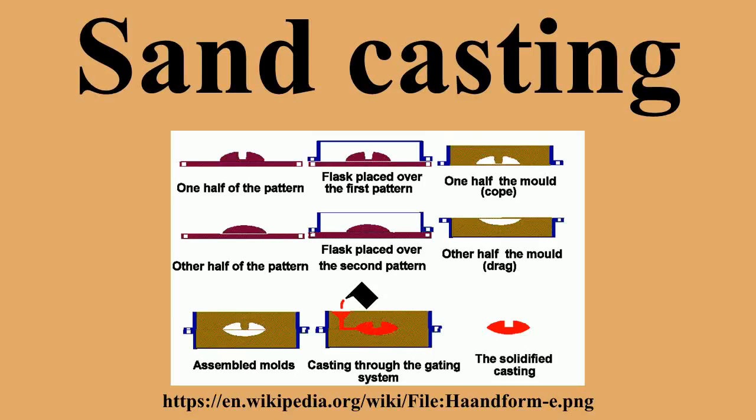Modern match plate molding machines are capable of high molding quality, less casting shift due to machine mold mismatch, and consistently stable molds for less grinding and improved parting line definition. In addition, the machines are enclosed for a cleaner, quieter working environment with reduced operator exposure to safety risks or service-related problems.